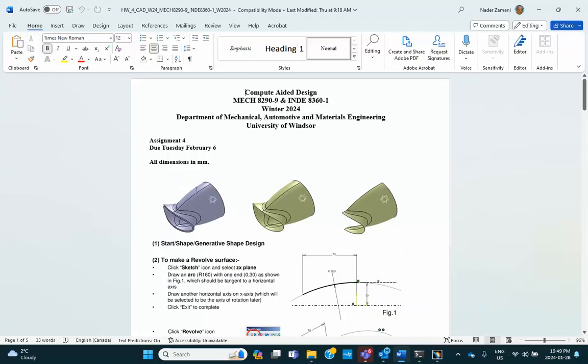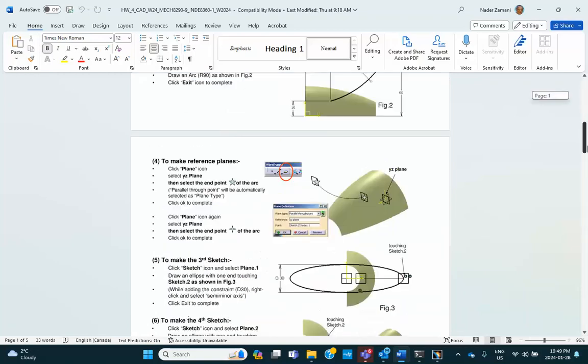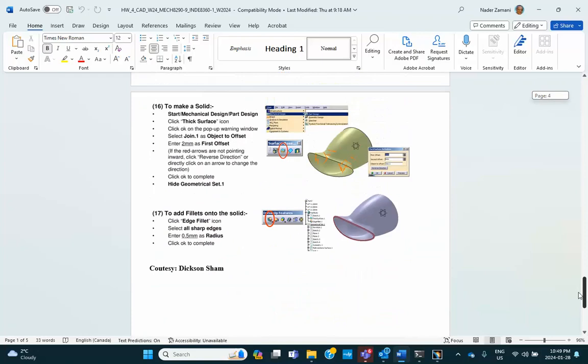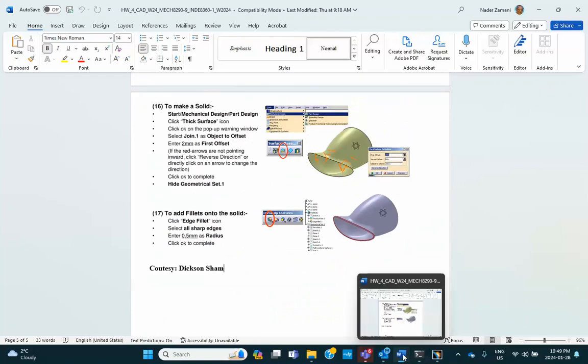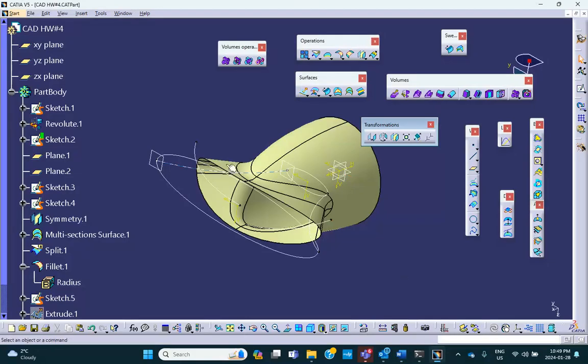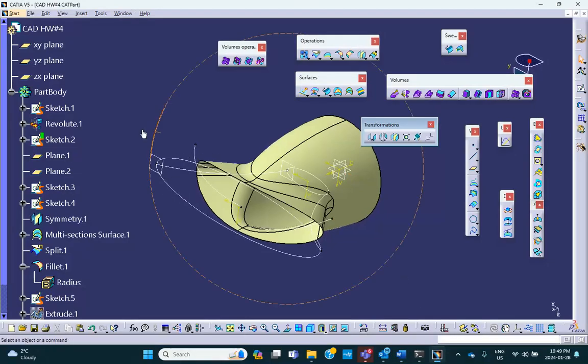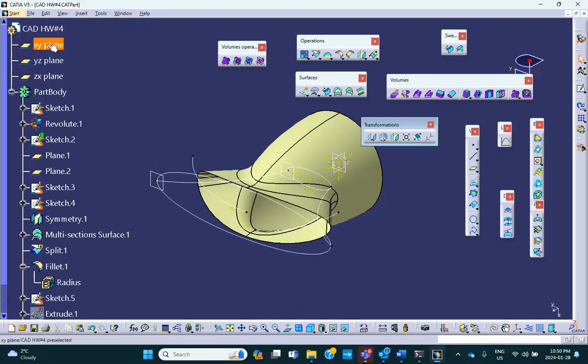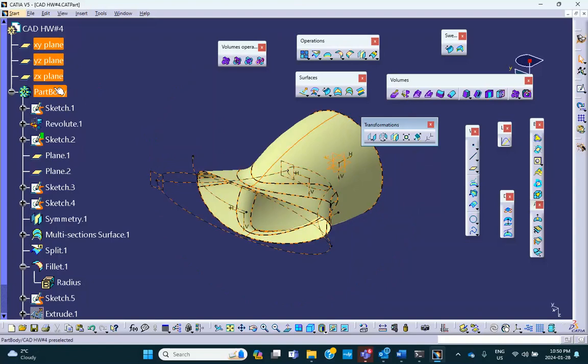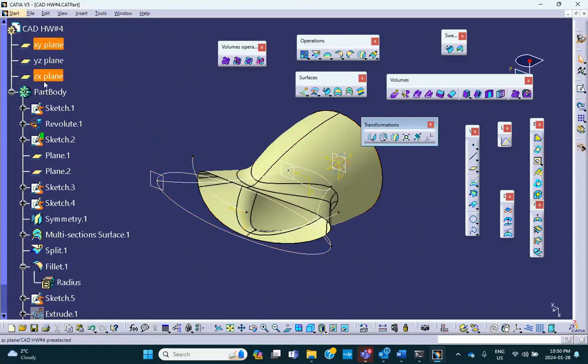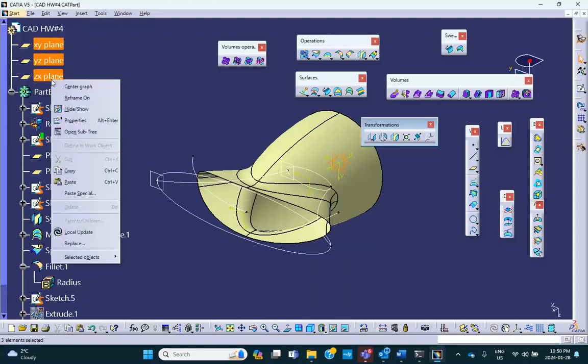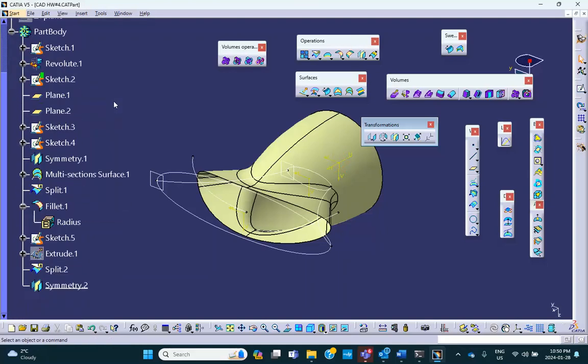All we have to do is to thicken it. So let's go ahead here. Last step, we go back to Catia. By the way, anything that you don't like, you can hide. So all these plates that we don't want, this guy all the way to that fellow. Hide. I'm using a shift button.